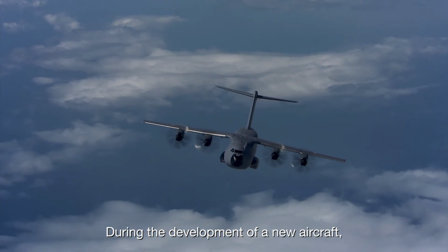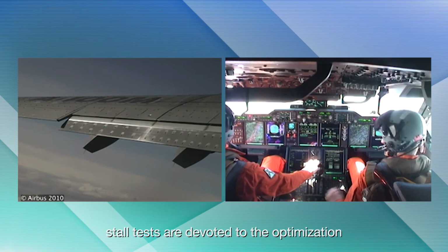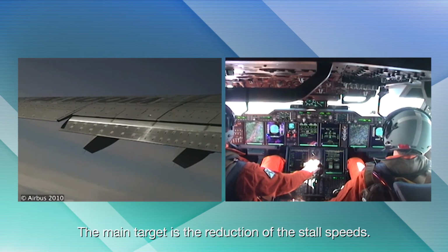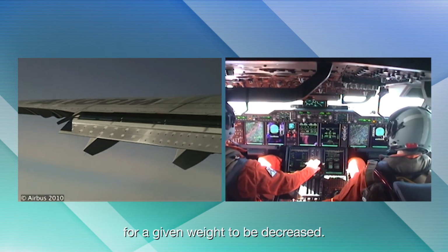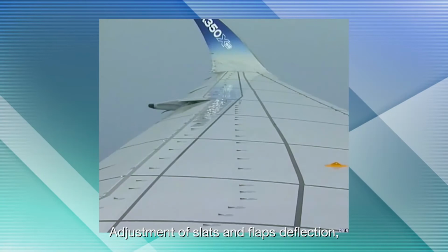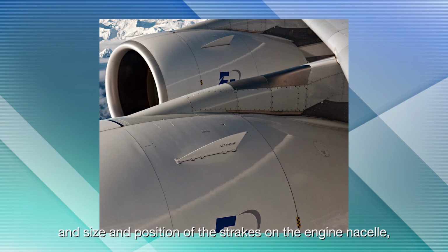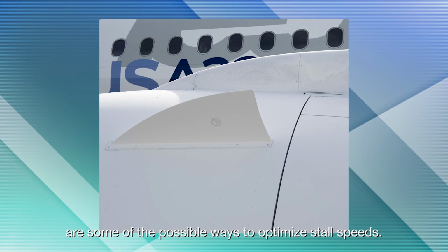During the development of a new aircraft, at the very beginning of the test period, stall tests are devoted to the optimization of the various aerodynamic configurations. The main target is the reduction of the stall speeds. In many cases, it allows takeoff and landing distances for a given weight to be decreased. Improved performances also reduce the noise footprint. Adjustment of slats and flaps deflection and size and position of the strakes on the engine nacelle are some of the possible ways to optimize stall speeds.